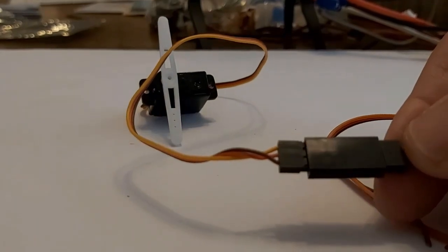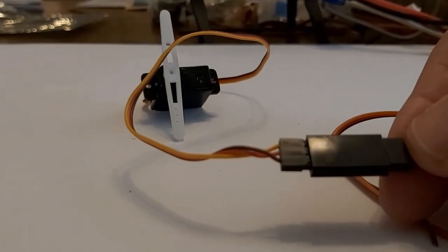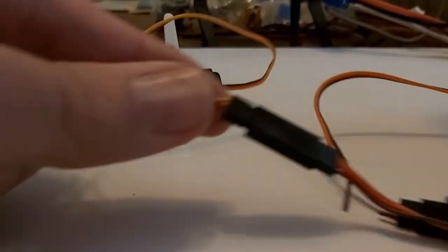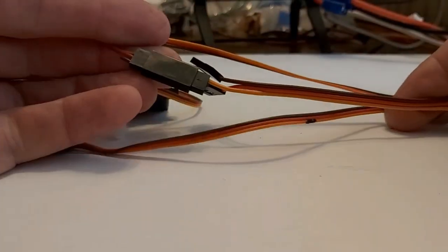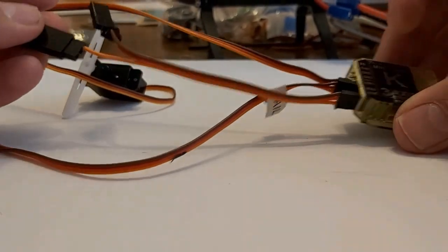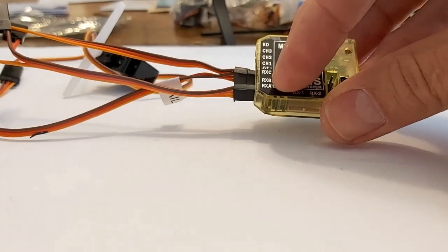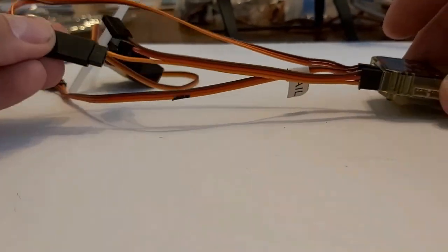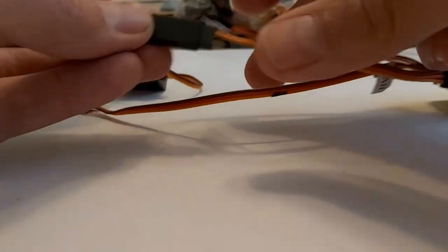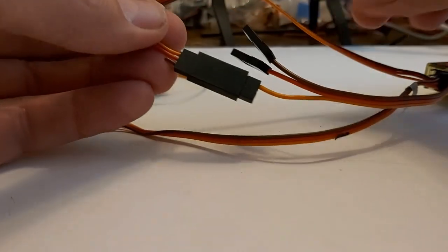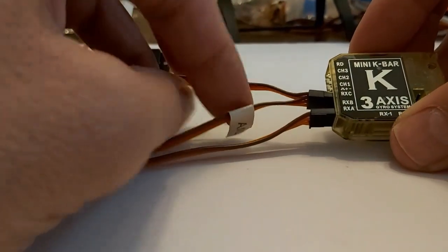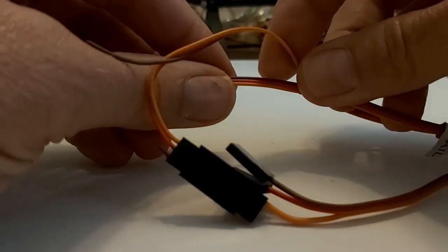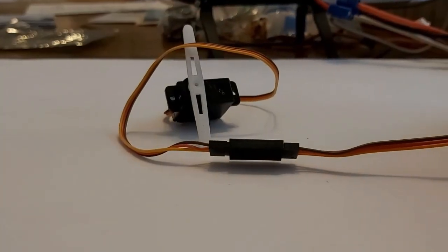All right, so now what I'm going to do is hook this up on the actual helicopter, and then show you what the controller looks like there as well. But just in summary, there's the breakout cable that kbar supplies with you. One end is hooked into the RxA. It comes out. I want the bottom pin, which is the orange one. That plugs into one end of my Y connector. The Y connector traces back, goes to RxC. The other end of the Y connector comes out and gets on over here to my servo.